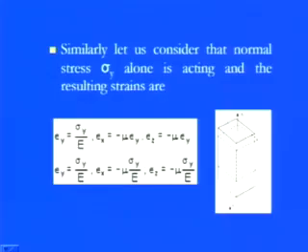Similarly, if you are talking about the y direction, if the normal stress component is in the vertical direction, meaning now I am pulling from the vertical direction, there is an extension in the y direction. So what will be the impact? You can see the figure here, where we have a rectangular bar, and from the extreme corner there is an extension. So sigma y is there, and due to that you can see this kind of extension here. This is extension 1, this is extension 2.